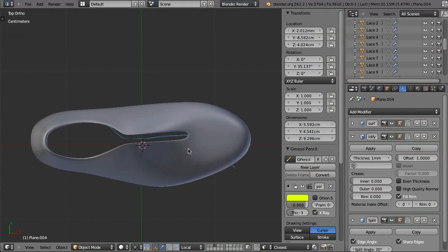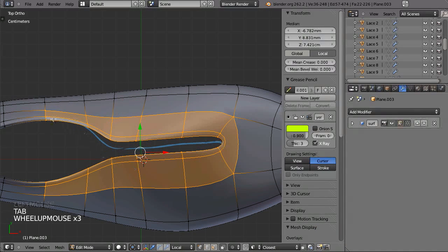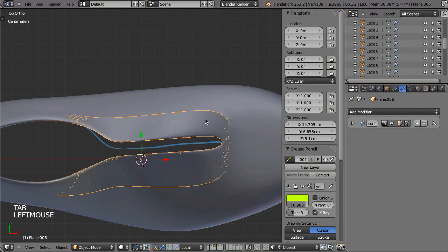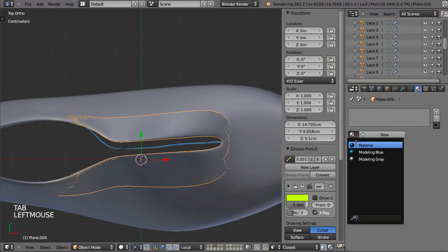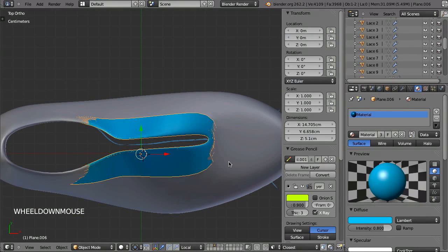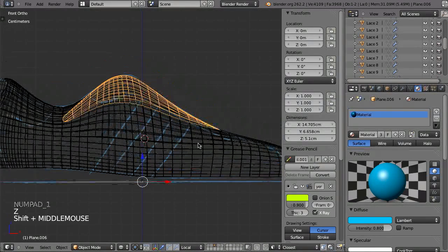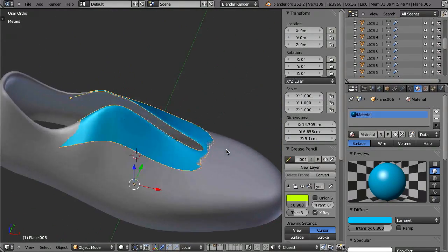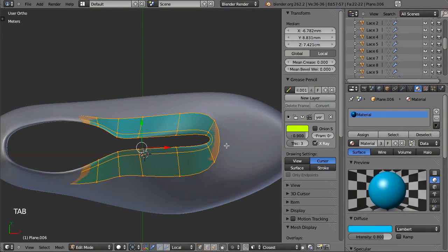Okay, so to build those parts, we can actually make use of the original shoe model. I'm going to move this one away. I have, for example, those faces already selected. Could Shift D, duplicate them, press P to separate them, move them out, and also here I'm going to give this a material color, and it slightly really sits on that surface, which is actually quite nice.